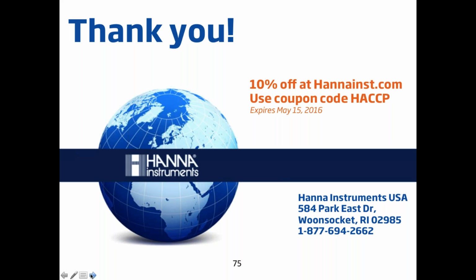We have one more question about how specific cleaning solutions should be. If your cleaning solution isn't dissolving or removing what your sample matrix is, then there's really no point in doing it. So if you're working with something that is really fatty and has a lot of oils, typically a basic cleaning solution will dissolve those fats more appropriately. Think about when you wash your laundry. We use a very specific laundry formulation because it's made to remove dirt and grease. If we used dish soap in our laundry, that wouldn't effectively clean it. So it's the same kind of parallel when we're thinking about cleaning solutions for our electrodes.